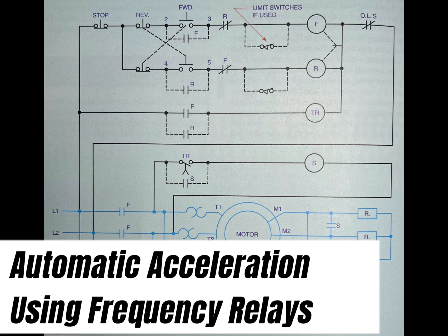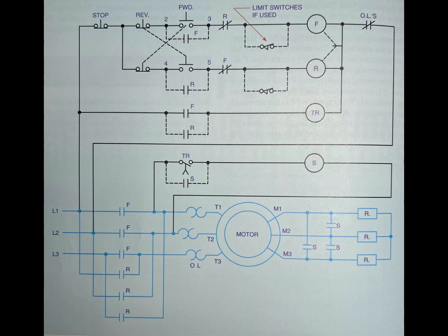In the above image, the voltage between the phases of the secondary circuit decreases in the same proportion from zero speed to full speed operation. At zero speed, the voltage induced in the rotor is determined by the ratio of the stator and rotor turns. This action is similar to the operation of a transformer. The frequency, however, is the same as that of the line supply.